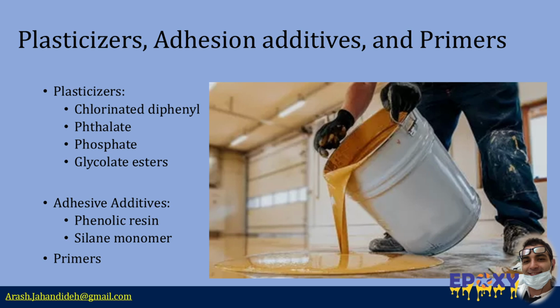These are designed for compatibility with the sealants, and they are typically supplied by the sealant manufacturers. Finally, low solid sealant primers provide monomolecular films that are highly effective in promoting adhesion to metals, glass, and ceramics, making them indispensable in many architectural and industrial applications.